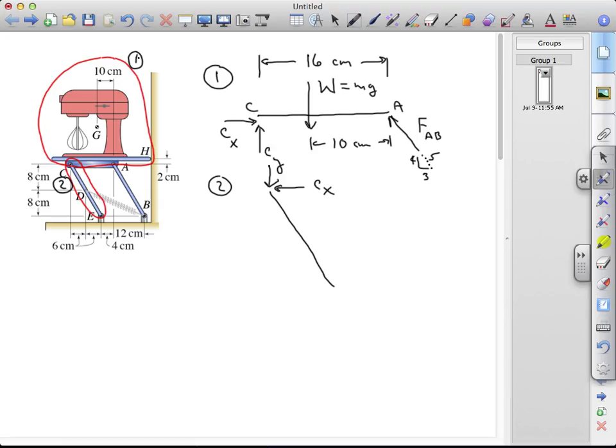For the spring, that again is treated as a two-force member. Its geometry is not quite as clean as the 3, 4, 5 triangle. I'm going to go ahead and represent this as FBD. Here the spring is in tension, so it's pulling on CDE. And you'll notice from the geometry of this that we have a rise over run of 8 over 22. That doesn't give us a clean integer value for the hypotenuse. This is going to be the square root of 548. And then we have a pin support at E, so we have EX and EY here.